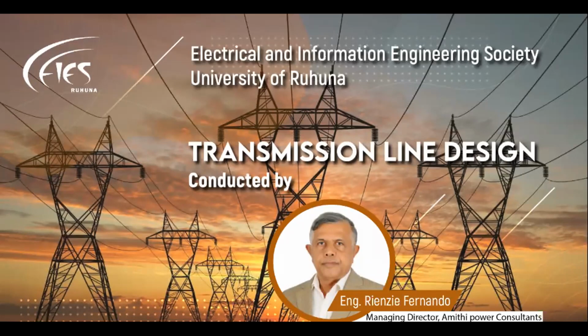To my mind, of course, when it's a sea area, when you have sea pollution and also near the cement factory and all, even 31 millimeter per kV is not enough.